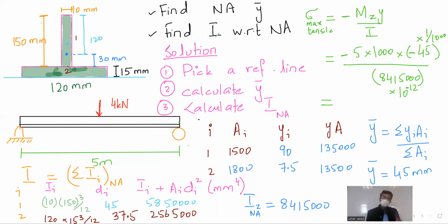No. Actually, this is not how it happens. I understand your question. For example, if these were two different pieces that we had welded, then many times it actually depends on the joining methodology. Many times the joint can become stronger than any other point. So when you're talking about the maximum tensile stress, the bottom surface will be exhibiting the maximum tensile, hands down. There is no qualms to it.